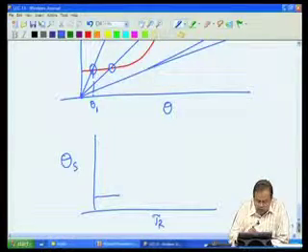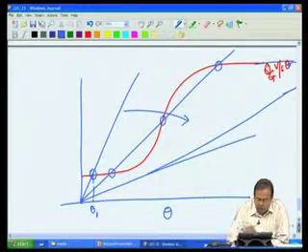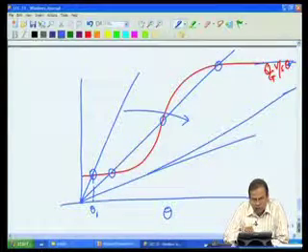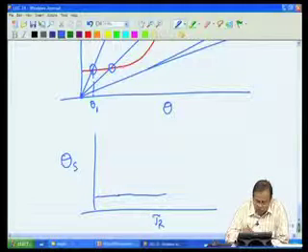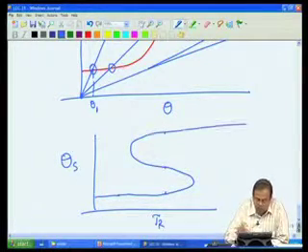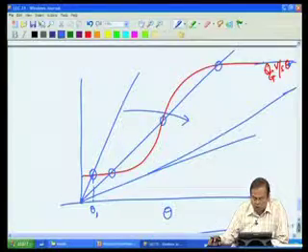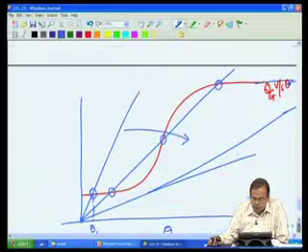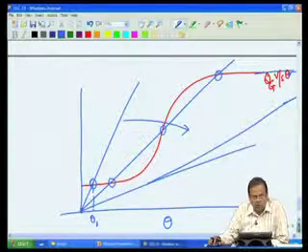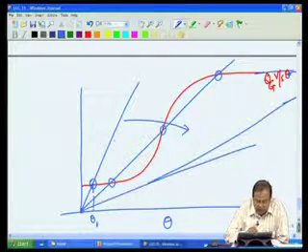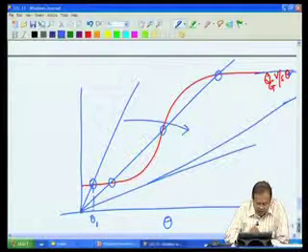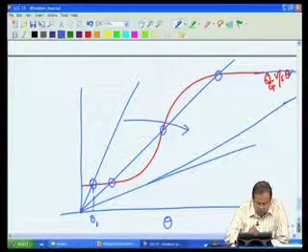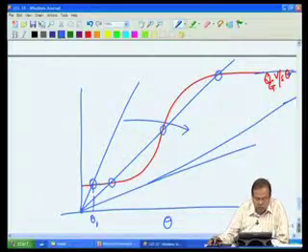As we keep decreasing the value of this slope, or increasing the value of tau r, what are we getting? We are getting three different values of steady state. So, this particular point, this point and this point, and we will have a behavior which we saw earlier. Okay. That is temperature. So, what will happen as we are changing the slope? If we are increasing the residence time, then we will have steady states which correspond to all these intersection points where Qg is equal to Qr, that means the lower branch.